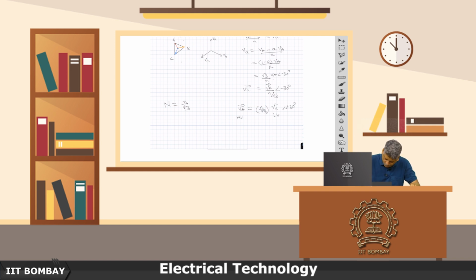All right. So, we have now calculated that the HV side voltage leads the LV side line to neutral by 30 degrees as we wanted, and because earlier we had a star delta as HV LV, now we have delta star as HV LV. So, what came earlier as effective turns ratio root 3 by N is now coming the other way round, the dual of it, N by root 3. So, that point we have captured.